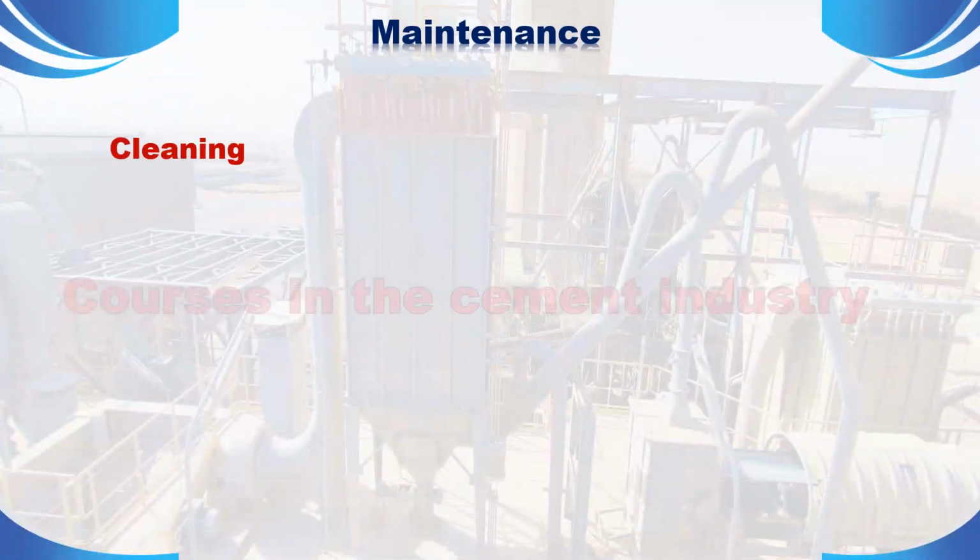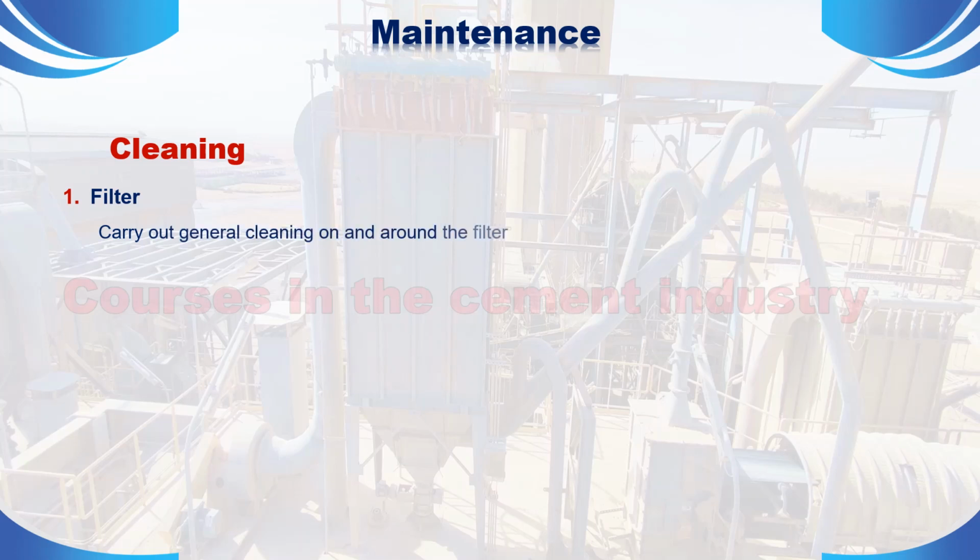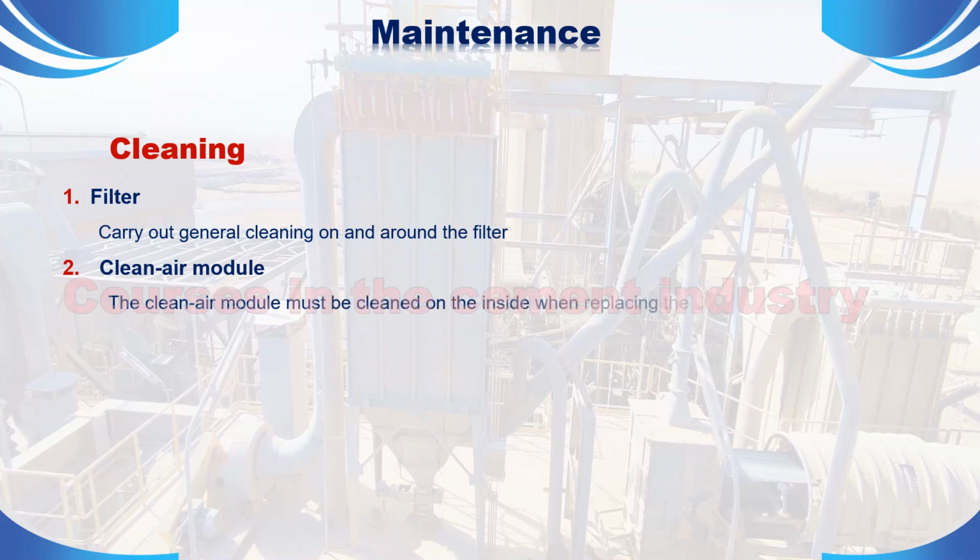Cleaning. 1. Filter. Carry out general cleaning on and around the filter. 2. Clean air module. The clean air module must be cleaned on the inside when replacing the filter bags, or cleaning must be carried out at least 4 times a year.